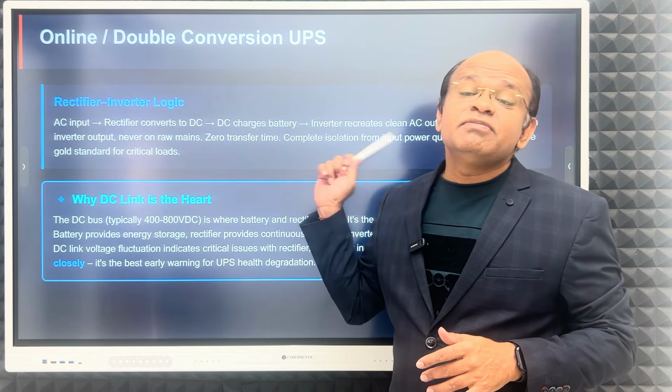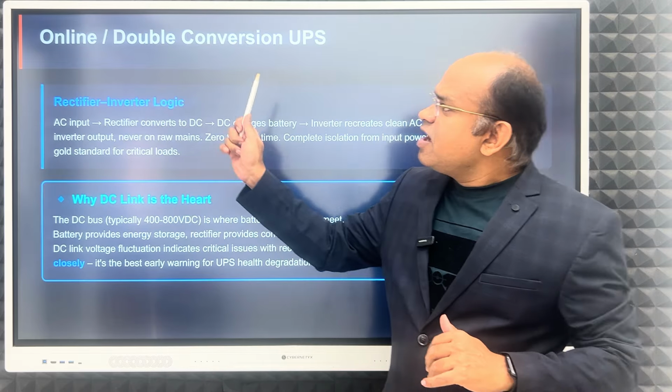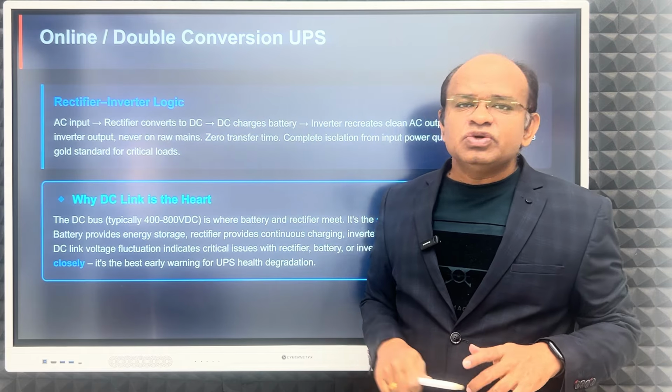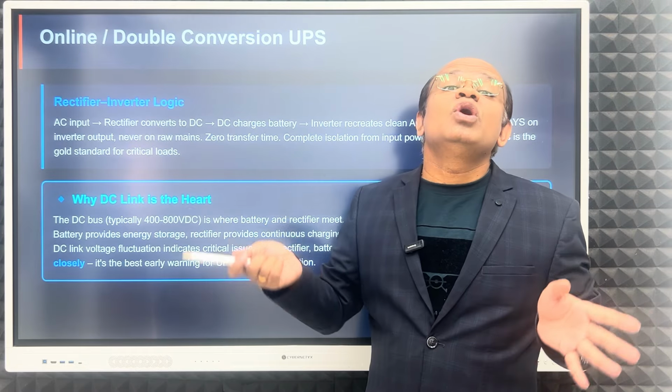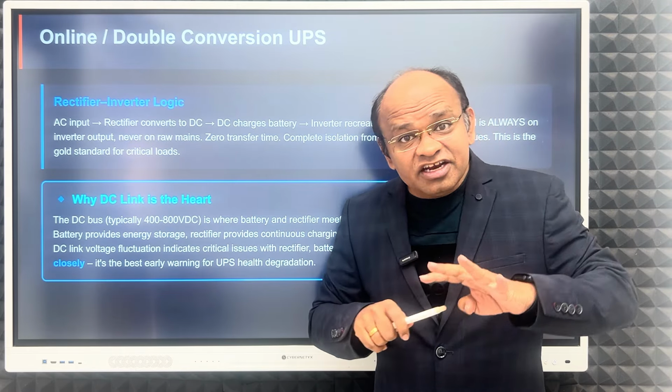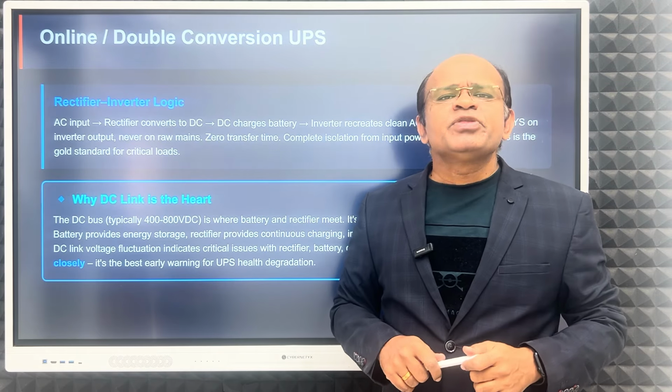Now, this is very much important. This UPS we use, online or double conversion UPS, it is called. Why double conversion? It converts AC into DC and again it converts it into AC. That is why it is called double conversion.